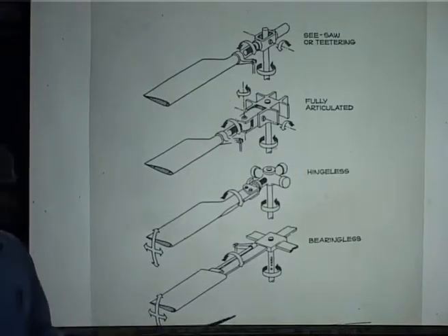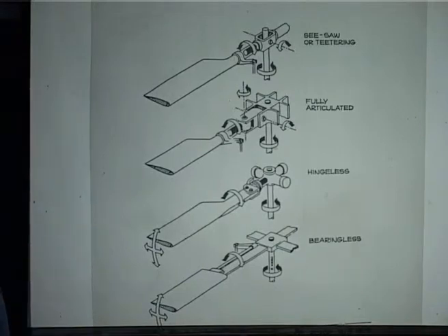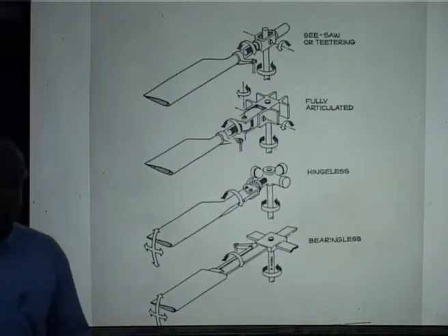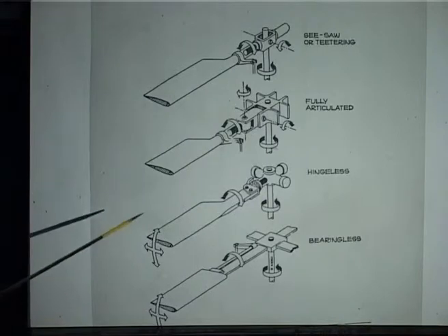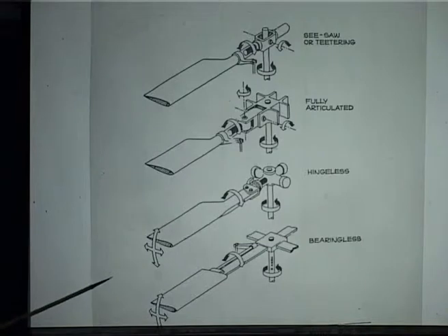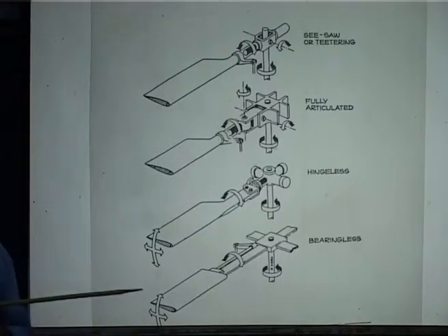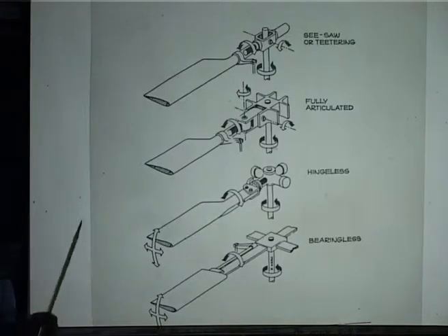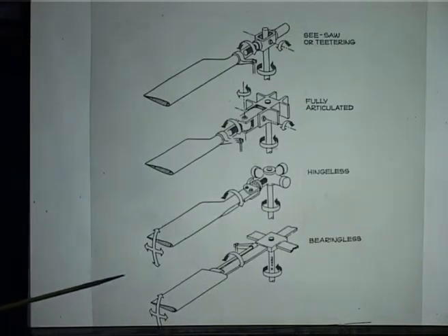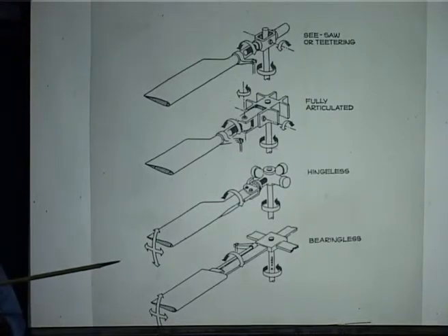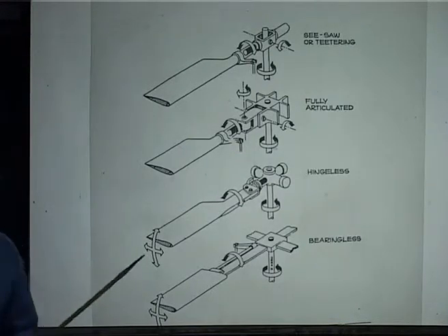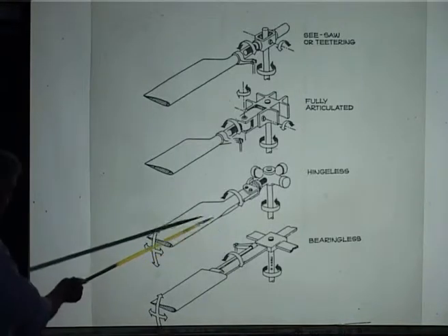But how you design it? That is why I said that when the manufacturing technology changed from metal to composite, please understand, metal to composite, only then did the realization of a hingeless blade become possible. By putting layers of composite cloth, or pre-preg, you can adjust the stiffness of this particular region.